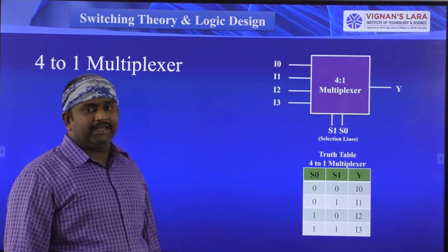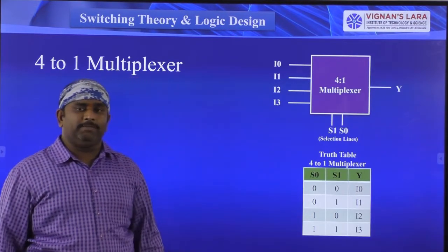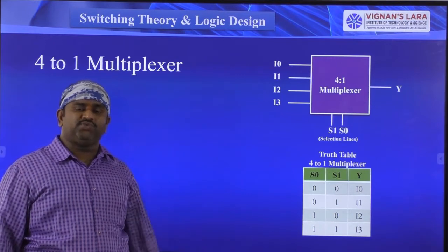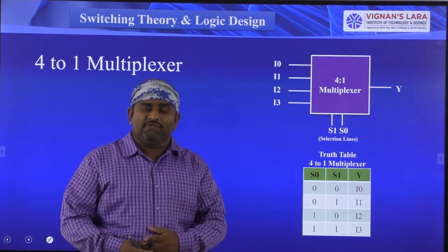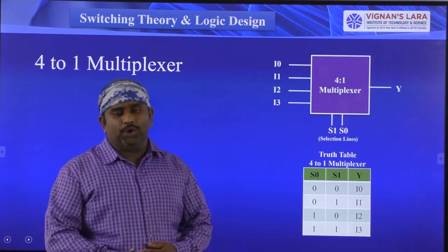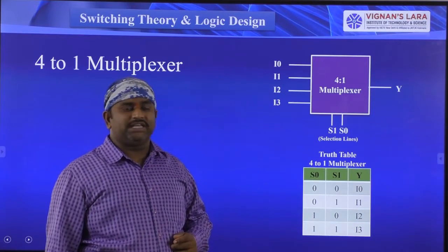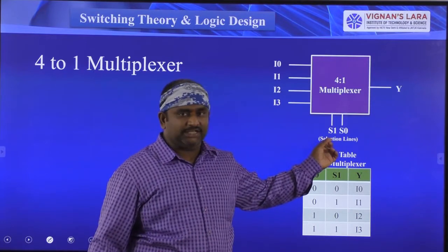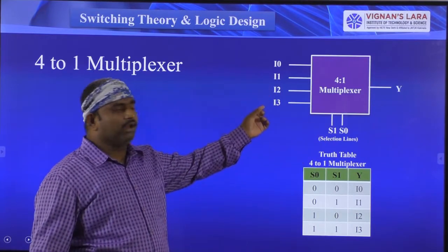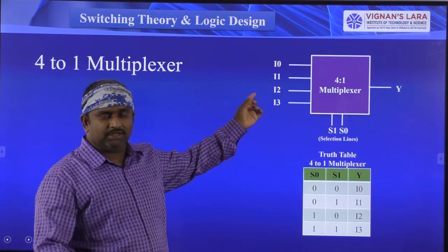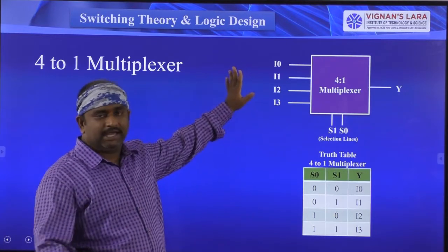Okay, right. Let us see the 4:1 multiplexer operation for implementing this universal shift register. For implementing the universal shift register, we have to know the 4-input multiplexer. So here I am taking the S0, S1 signals as selection lines. Here are I0, I1, I2, I3. I will discuss what these 4 inputs are in the next slide.